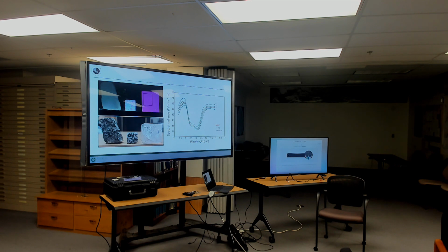There are two main classes of detectors. One is a photon detector, and we've spoken about that a load, right? A semiconductor where we have the valence band, the conduction band, and we're using the photoelectric effect to cause loosely bound electrons to join a current. The other type of detector is a thermal detector, which works a bit like a bimetallic strip. You have a similar thing, an array with pixels, but each detector is a blackened metal flake that just absorbs light.